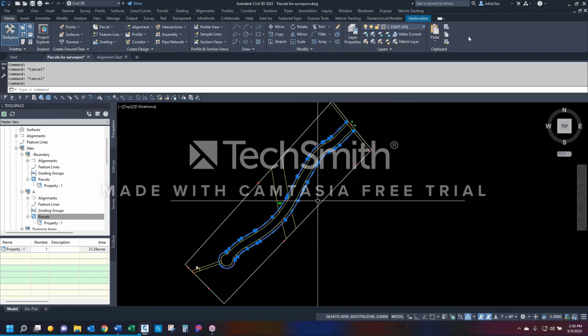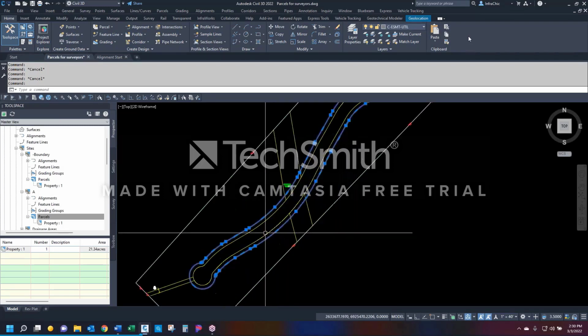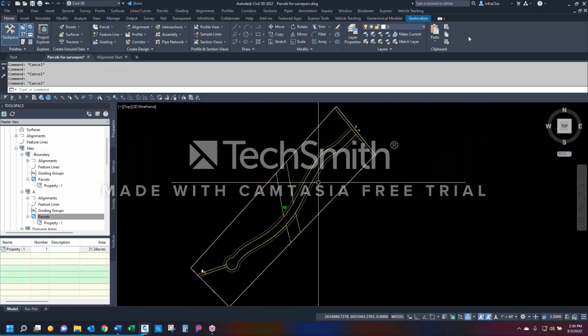This gray line represents a 20-foot private utility easement, which, because of the way Kaufman County is set up, they do not allow you to put water and sewer within the roadway perimeter. You must put it on the outside and put it into your private network. But because it's a utility easement, the area between the roadway right-of-way and that utility boundary can be included in your lot information, in your lot square footage or area. It's not a drainage easement, it's a utility easement.